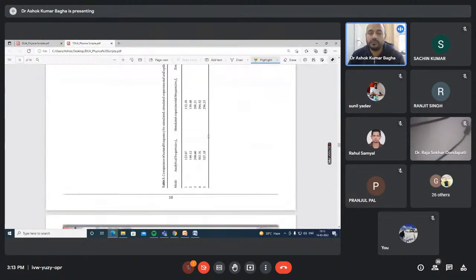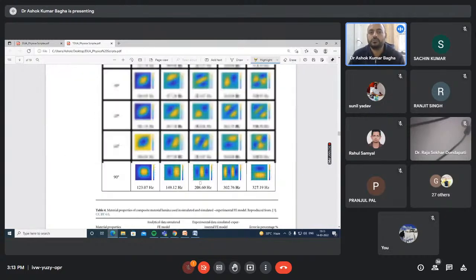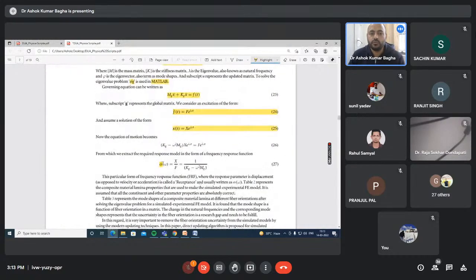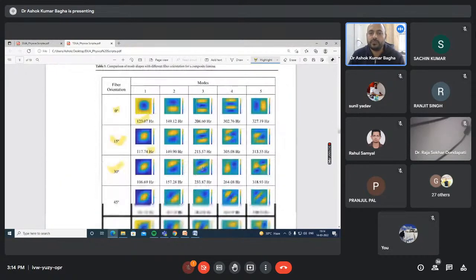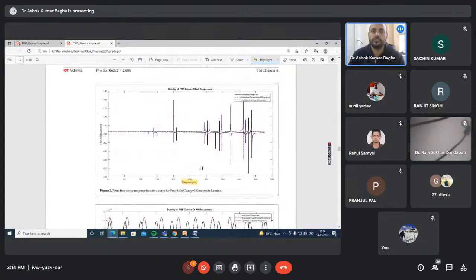So it means that the orientation has an effect on the natural frequency of the system. Again, this morning Dr. Shraddha Pradhan showed you the FRF, by solving the eigenvalue problem or by using the EIG command. Again, I will show you here this alpha he showed you today. There is a great advantage of this. You just solve it with different values of omega. You know the K matrix and M matrix, and you can plot the frequency response function curve.